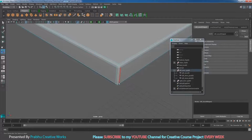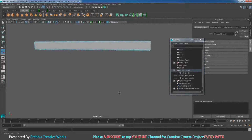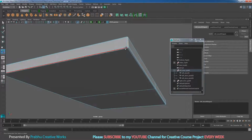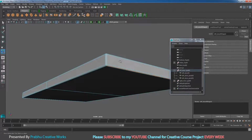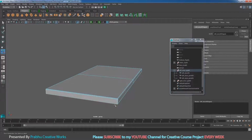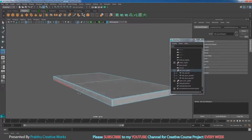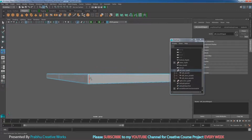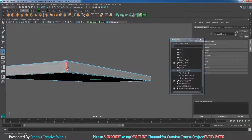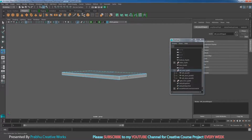Double click on this edge and then you want to shift double click on this edge and then shift double click on this edge. So you want to select this 3 corners over here. Don't select top side. You want to only select the side and bottom. So you want to do same thing on that side. So shift double click on this edge and shift double click on this edge and shift double click on this edge. So don't select the top one.